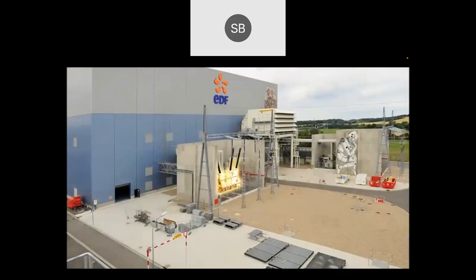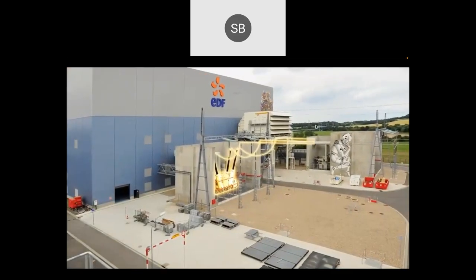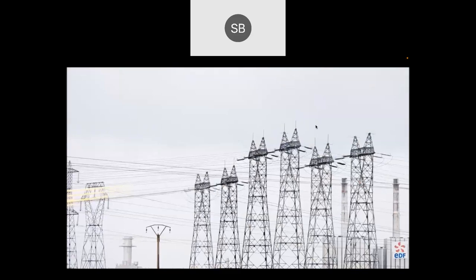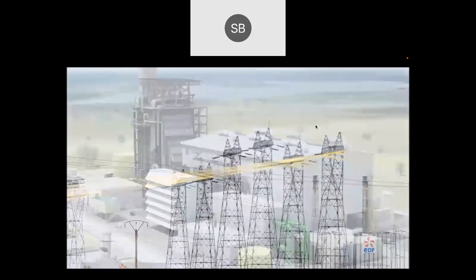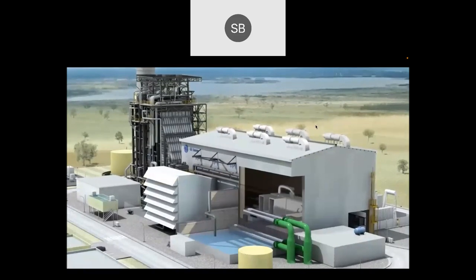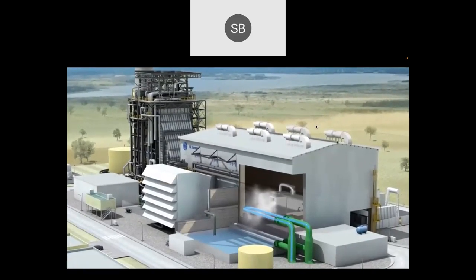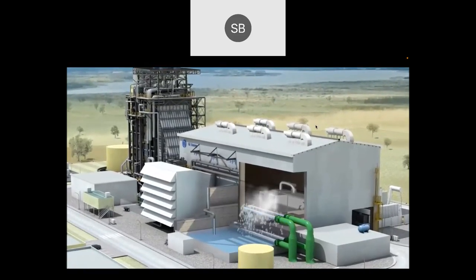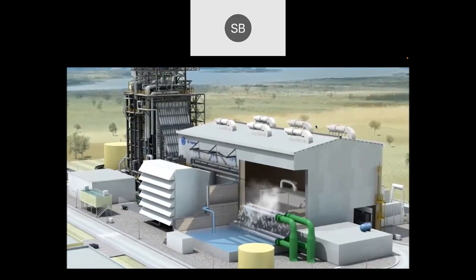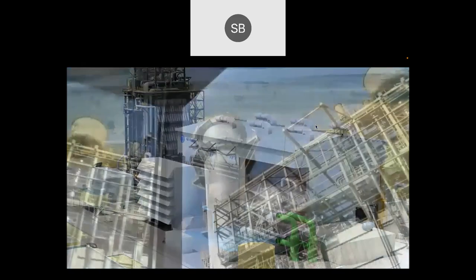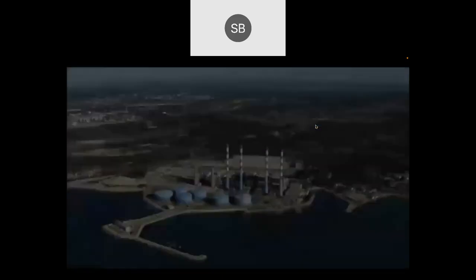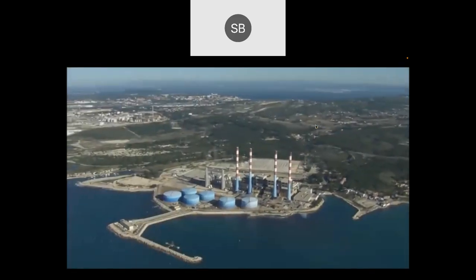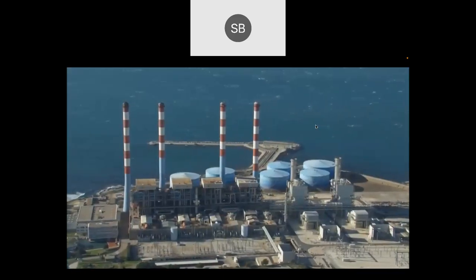The energy produced by the rotation of this second turbine is transmitted to the generator, supplementing the energy already transmitted by the combustion turbine. In the generator, the interaction between the electromagnets of the moving rotor and the copper coils of the stationary stator produces an electric current. Transformers boost the current's voltage to between 225,000 and 400,000 volts, thereby facilitating transmission over the grid's high voltage power